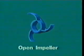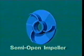Open impellers basically are vanes mounted on a shaft with just enough backing or shroud to keep the vanes rigid. Semi-open impellers are completely covered on one side of the vanes. Closed impellers have shrouds covering both sides of the vanes. They also have a central hole or eye on one or both sides. That hole lets fluid enter the impeller.